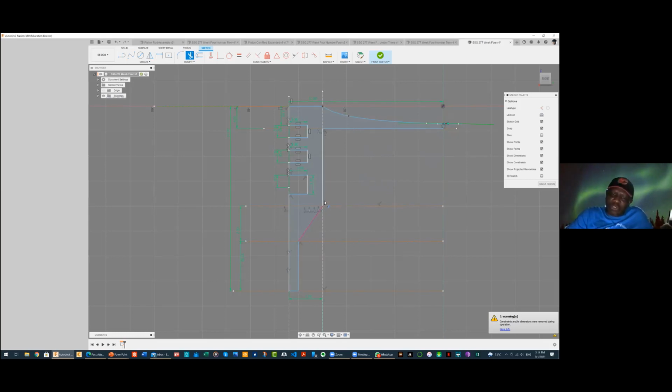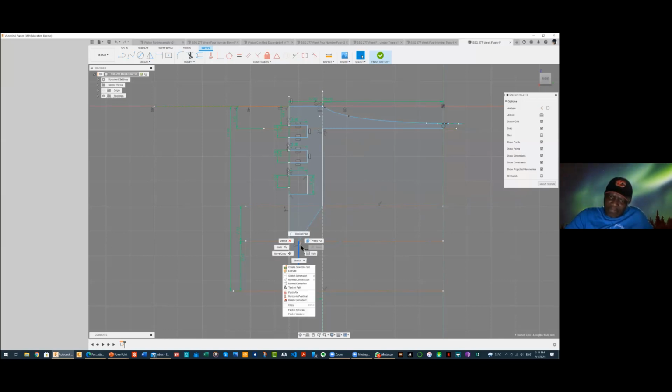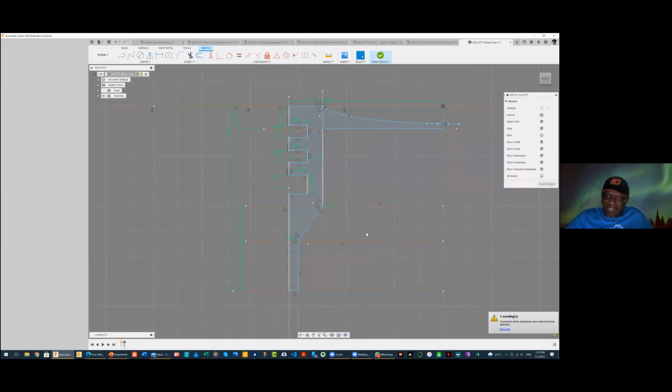You may also want to do some filleting. Want to fillet this and this? If you accept the suggestion, you might want to fillet this line and this line. You can repeat fillet. Choose this one and this one and accept the suggestion there. So that's another fillet there. So everything is still okay. There are several other enhancements you might want to do.